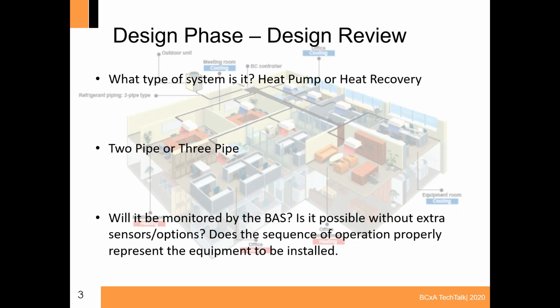If the office space is cold and it has the majority of the indoor units on it, and the server room is hot, you may have situations where the system will switch to heating and heat the server room. So you may want to recommend the engineer place all server, electrical, MDF, and other similar rooms on their own dedicated system.